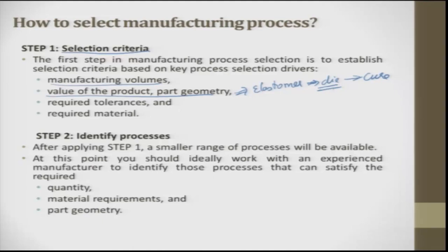If you want to hold the die and then machine it, you can't do it on a lathe machine which has a horizontal axis. So what we do is try to mount the die, which is around a meter, again circular or cylindrical, on a chuck with the tool on the vertical axis.